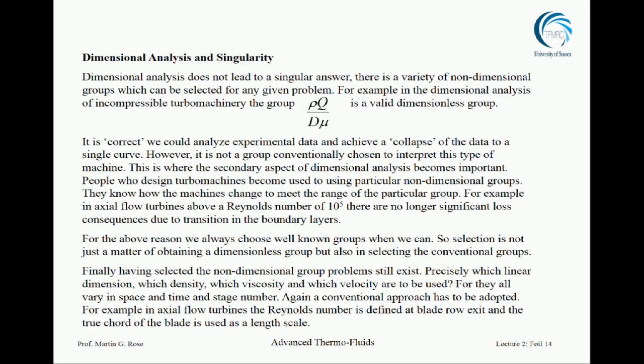So, if it's not constant during the process, then why is it so important? Because the level of the Reynolds number actually tells you something about the way the fluid is going to behave. If you ask the question, what does Reynolds number mean? You'll find in the textbooks, it says it's the ratio of inertial terms to viscous terms. So it tells you, broadly speaking, how much force the momentum of the fluid can generate compared to how much force the friction of the fluid can generate. And the size of that number tells you the relative size of those two, and it changes.